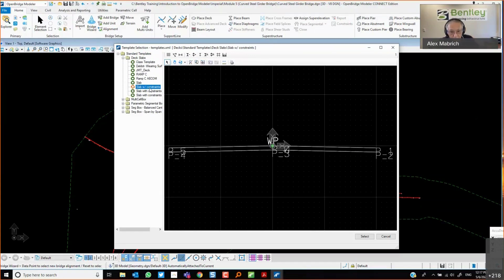If you don't take care of the templates beforehand, you gotta go modify the super elevation, modify the slope, place it. It will accommodate the bridge, right? It will be dynamic. Yes, it will accommodate the bridge. And then on top of that, you need to modify the piers too, right? Because you select a very generic template and not one for your project.